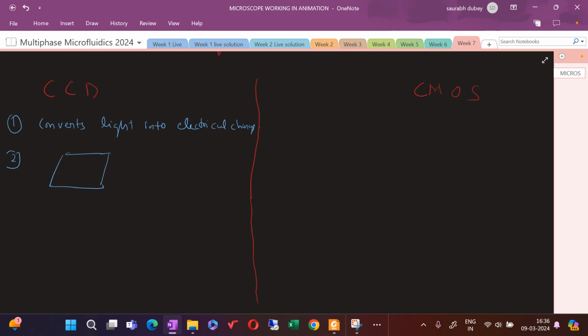A number of these CCD arrays will be placed. The pixels are charged by incoming photons and transferred through a very limited number of output nodes to be converted to voltage, buffered and sent off chip as an analog signal. All the pixels capture the light and the output uniformity is high.